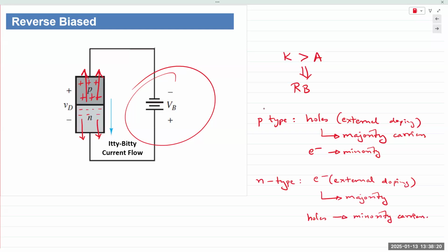Okay. And they're both free to move about in a lattice material. So energy can be transferred due to the flow of either electrons and holes or both electrons and holes. So in a diode, current flows due to the effects of both electrons as well as holes. Hence, it is a bipolar device, which when we get to a BJT is implied in the name itself, a bipolar junction transistor.